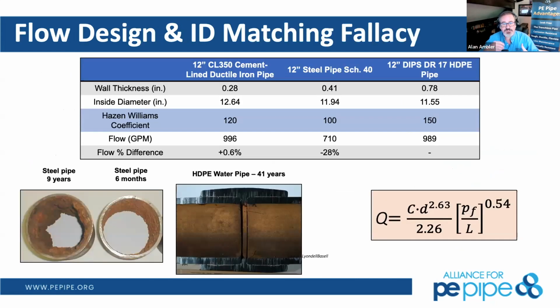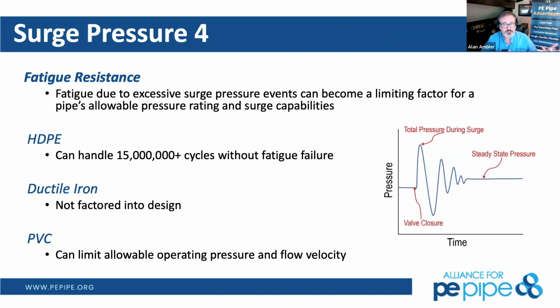Matt had mentioned semicrystalline and amorphous regions. Those, now in the 4th generation of poly, have been designed to address that cyclic fatigue. There are calculators available to you online, PPI's PACE, that'll let you make some assumptions and enter values that are right there, in order to spit out results and comparisons directly between pressure classes of ductile iron, PVC, and HDPE.